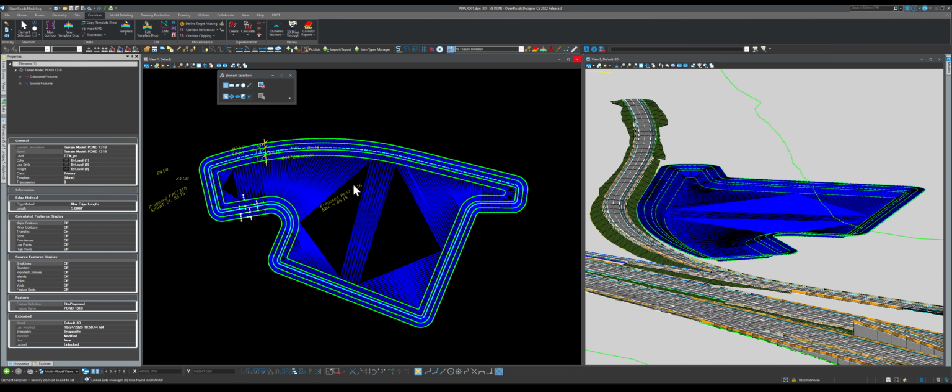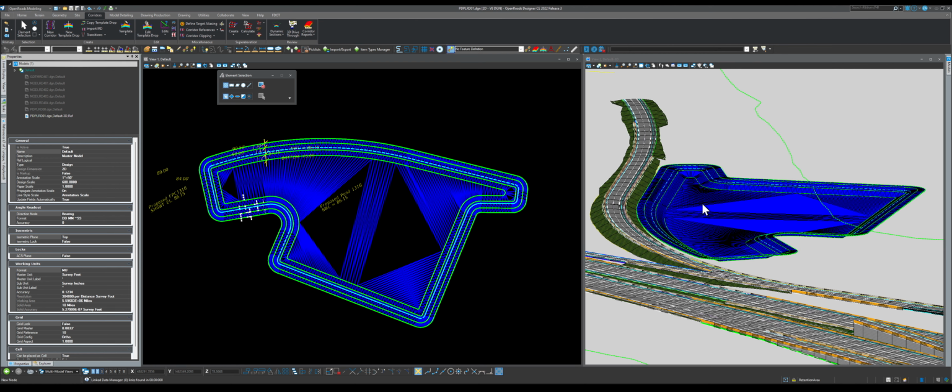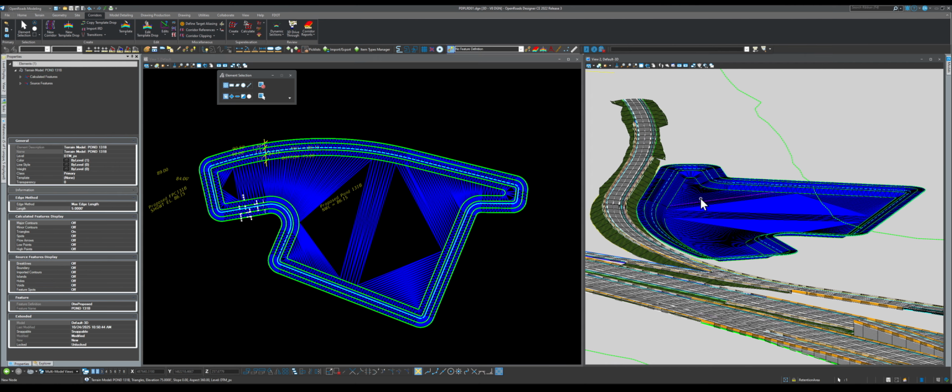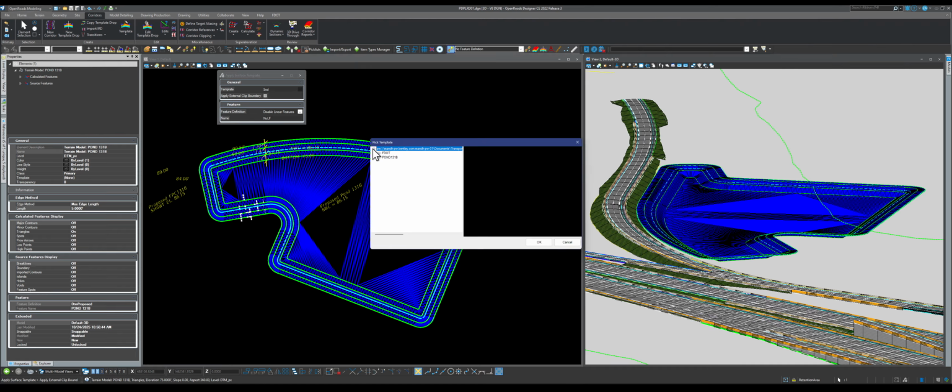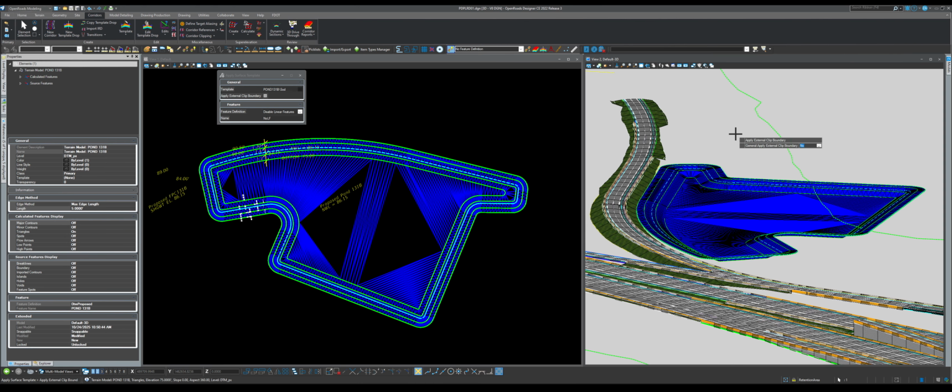Okay, so let's dress up the pond, right? Because like I said, I don't like it naked. So let's do this. Come here, hover over it and click. And then there is this thing here. See, templates? And then apply service template. And then after that, let's go to the template library that we just opened. And let's go to the pond. And you see sod? Pop, click on it. And do OK. And then click, click, click, click, click.